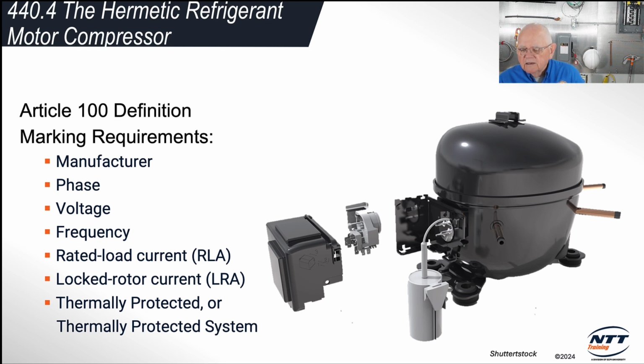We do have a capacitor down here. Sometimes it takes that extra kick, doesn't it, to get that motor started. So typically you'll see some type of starting capacitor associated with these refrigerant compressors. And a very common problem to have is, I can't get my compressor to start. Oh my goodness, my air conditioner's bad. No, it's not. Check your capacitor. If the capacitor's bad, you can't get that refrigerant compressor to turn over for you.